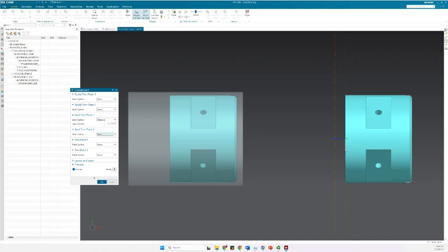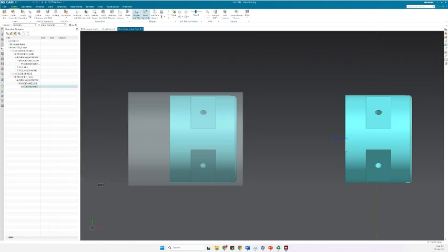So for example, if I put 5, it would be here, so it would be, for example, -10, or let's say -20, or actually looks like that is more or less -15, but to be more accurate, I would like to just define it by point here so that I know accurately where the point is. All right, so now I have defined the workpiece on the main spindle, on the sub spindle, and the avoidances and containment geometry.